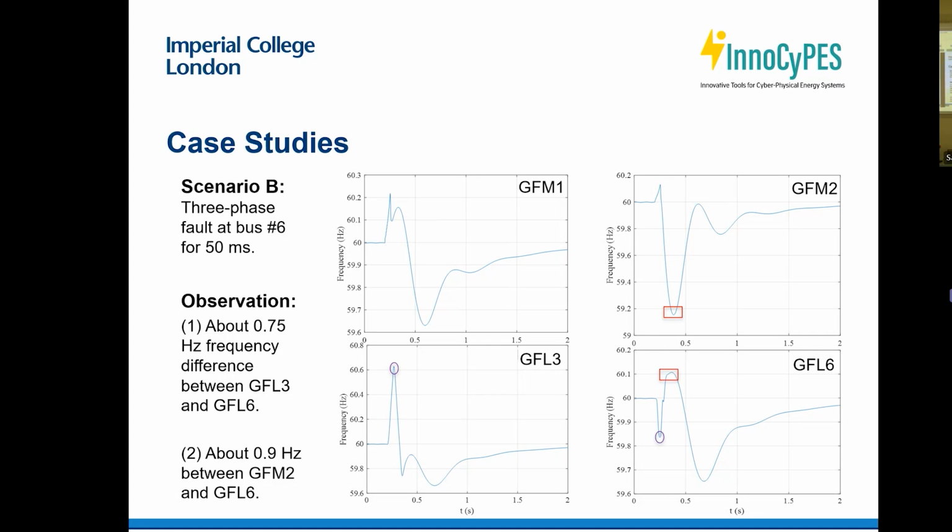This is something that did not happen in traditional grids, because in traditional grids there was a strong link between power and frequency. Now, because the PLL reads the frequency based on voltage, voltage has a predominant role in frequency control and synchronization.